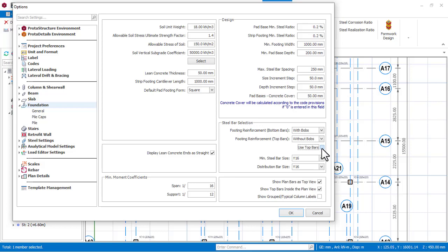Okay. Then also on this page that says minimum steel bars, I think in most of my videos I've said that when you're designing for a pad foundation and for a one-story building, keep in mind to use diameter 12. That is okay. 12 is okay to use, and don't use 16. 16 can be used for a 2-story building, 3-story building, and 4-story building.